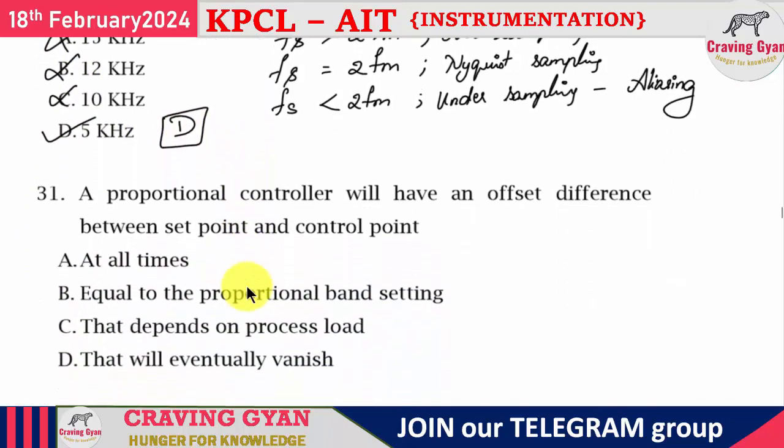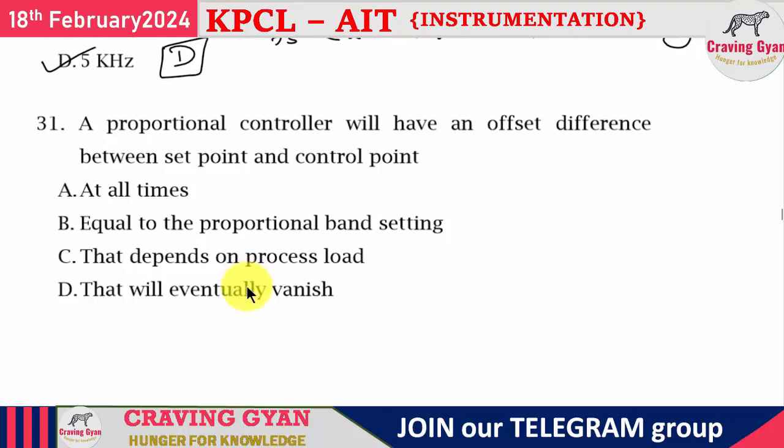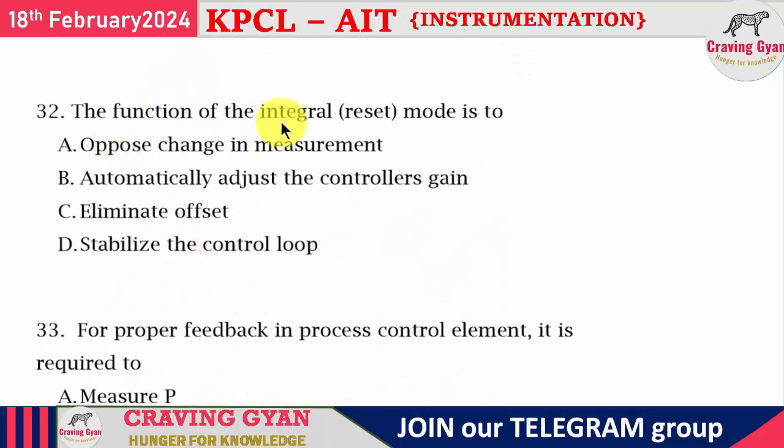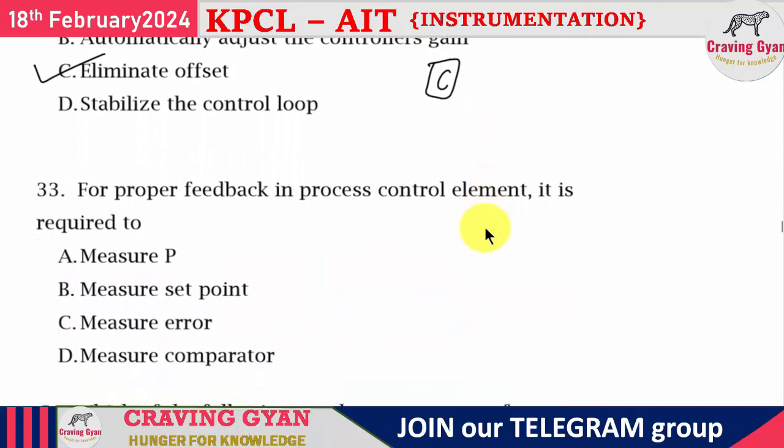Option D is correct. 31st question, a proportional controller will have an offset, a difference between the set point and the control point, that will eventually vanish. 32nd question, the function of the integral reset mode is used to eliminate the offset. Option C is correct. So straight away, direct questions they are asking. So no need to explain all the options.